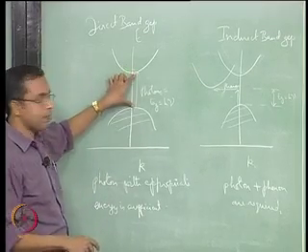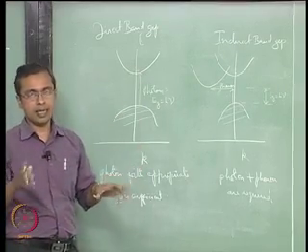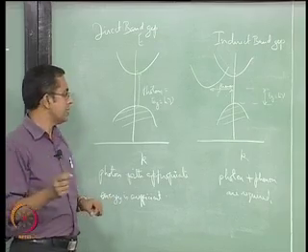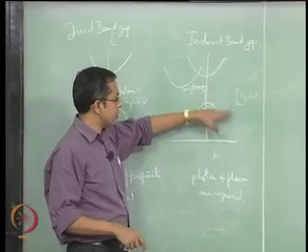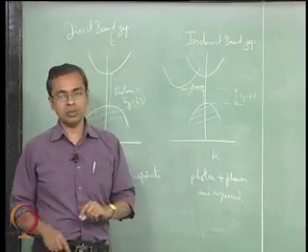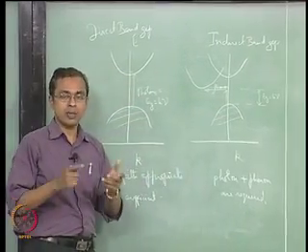The band gap is higher, so higher energy is there, at the same time the probability of transition is also high, so you get a higher energy beam which is also intense. In this case you get a lower energy beam because the band gap is smaller, but on top of it the intensity is also less because it is a two step process. The two step process is reducing the chances that it will occur, so you get a dull beam.